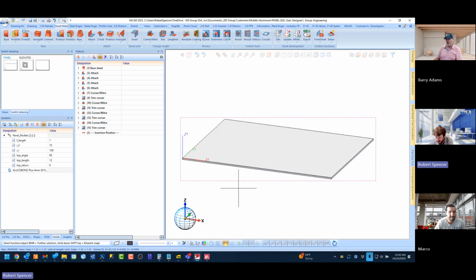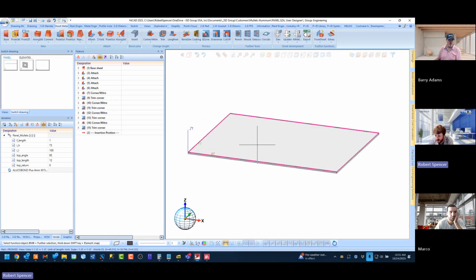So since we made a change, what do we now have to do? You have to update the catalog. Correct, apply it to the catalog. Yep. Here's my little trick for this. When I have functions such as top return or left or right or bottom, I switch it back to the standard configuration prior to saving, because whatever condition it's in when you save it becomes the default.